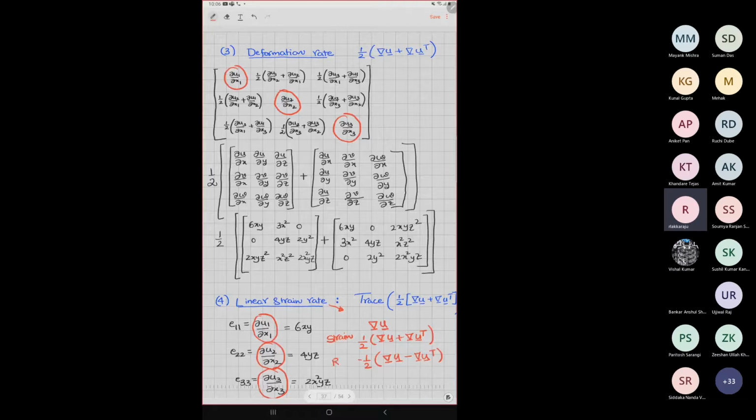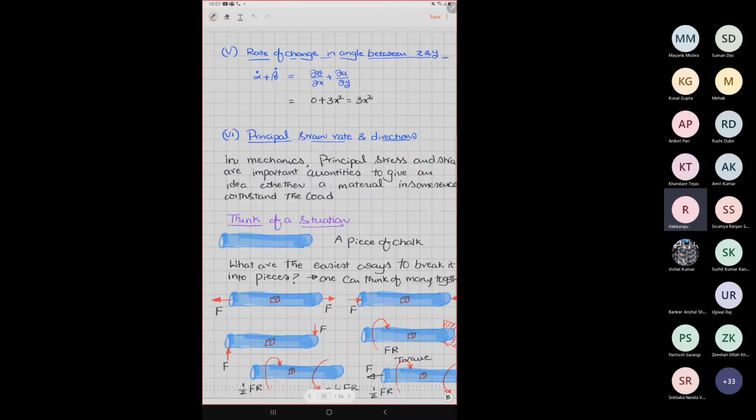In the strain rate tensor, we can look at individual components, the diagonal ones, to understand volumetrically how it is expanding or compressing, and angularly how it is getting stretched or strained. We understand this from the crosswise components. The pure rotational components we learn from the rotation rate tensor. These are the basic concepts we require to begin anything.